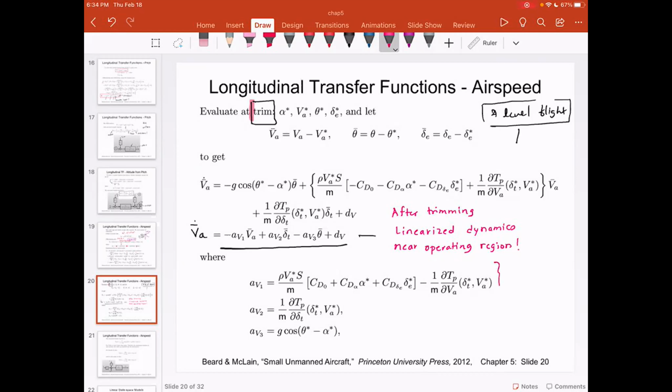The trimming can be done multiple ways. You can perform trim analytically, or you can perform it numerically, or you can perform some approximate techniques, something called a fractional way, where you take pieces of the block and come up with a linear approximation. So at the end of the day, what will come out of trimming is a very simple linear representation of very complicated dynamics.